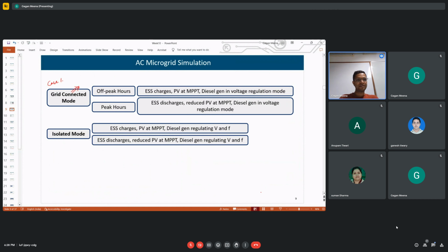First one, steady state: the Q requirement is very less, because steady state is steady state, so the disturbances are very small. Load-generation imbalance is very less. So here the Q requirement is very less, less than 40%, much less than 40%. From this state we can move to any of these states depending upon the voltage level in the system and the Q requirement.